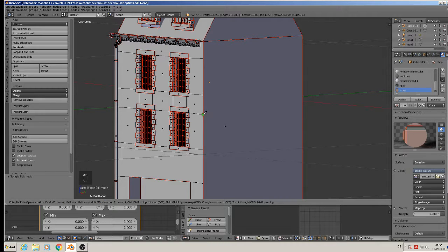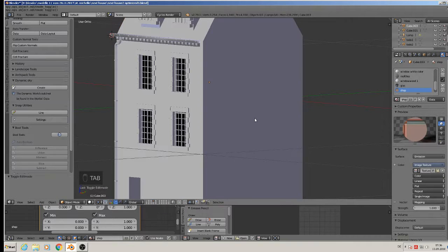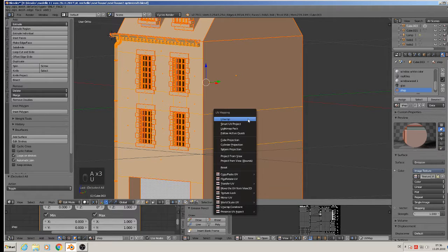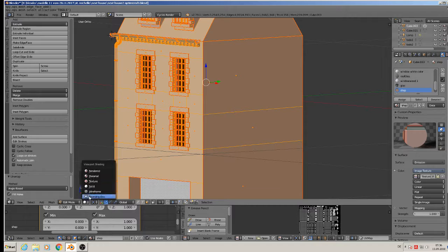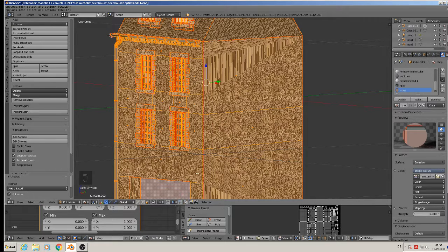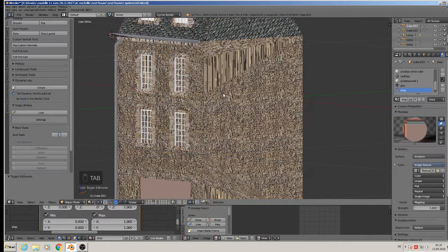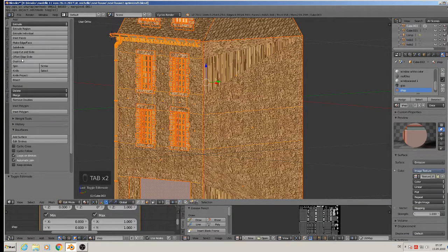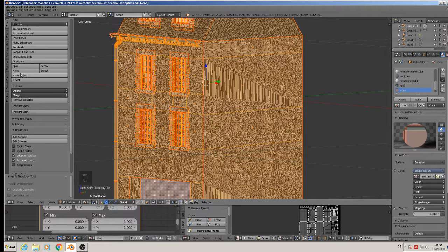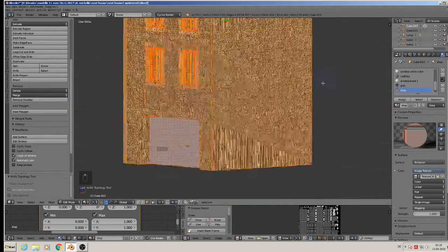So we take a knife, bring it simply there and spacebar to cut, and then we unwrap again and we will see that failure is gone or not. So you unwrap again. Now the failure is there and there. Yeah, it needs to cut it in the whole direction. So it means there and there too, and here.